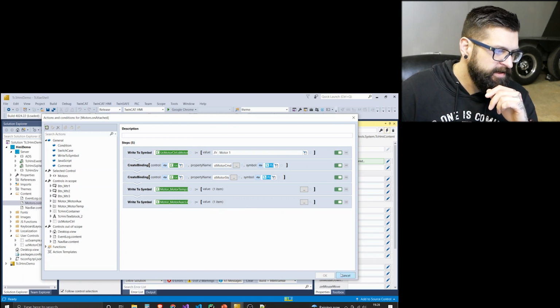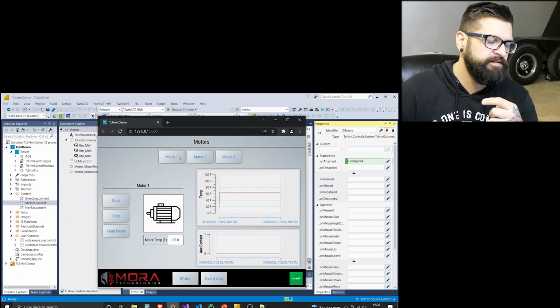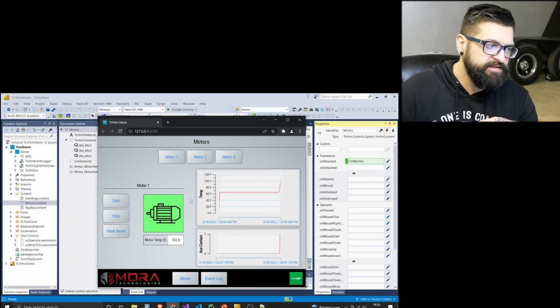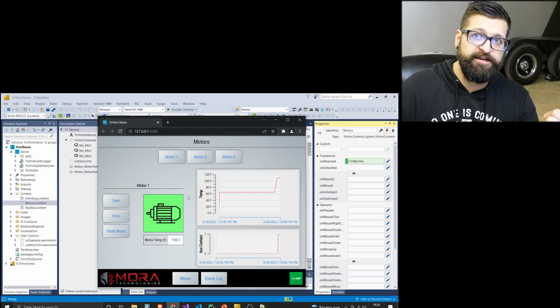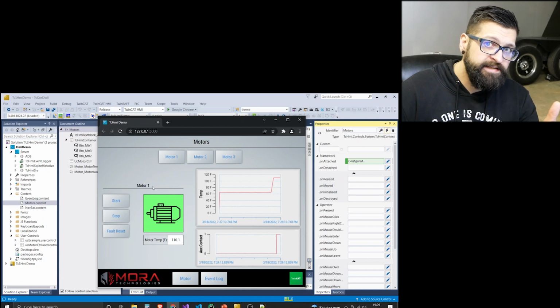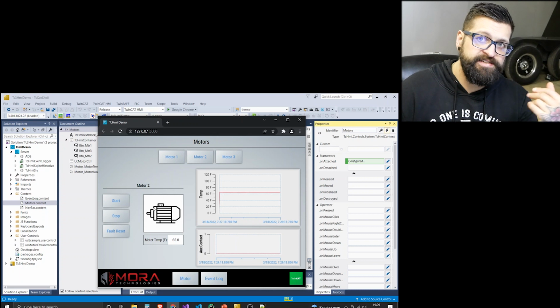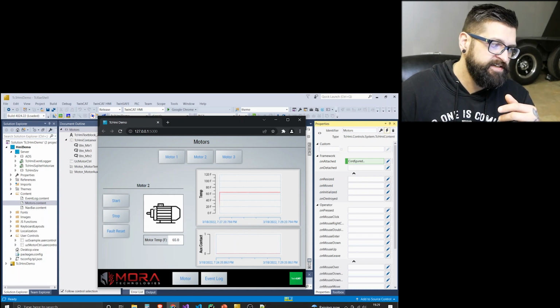So if we go back to our HMI, I think you can kind of see what we've talked about. This is one user control that has parameters. As I click on these buttons, I am triggering an event that is either going to pass by value the motor title, so it's passing this motor title right here, or it's making a living binding, so pass by reference, that's linking between the PLC and the HMI, so that as I start and stop these motors, it's retained.